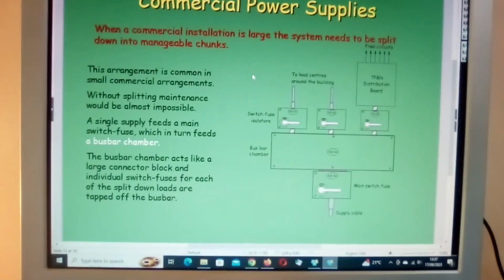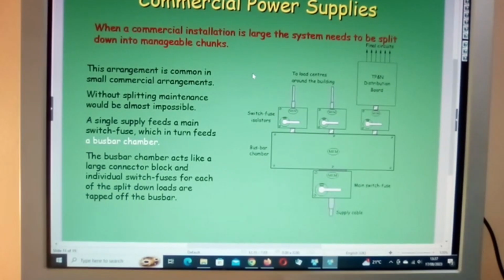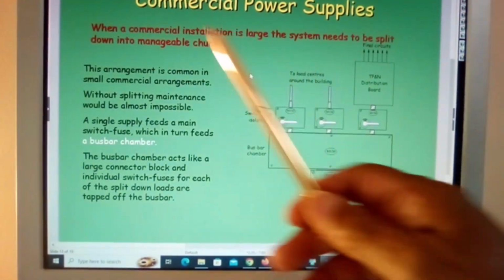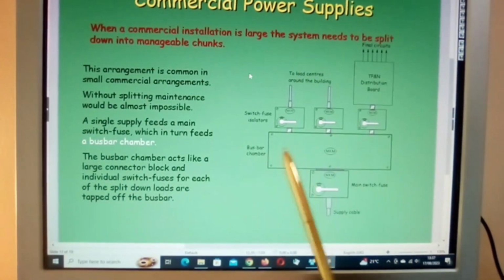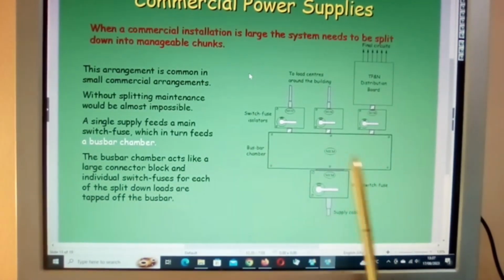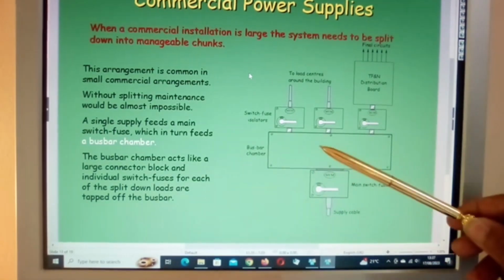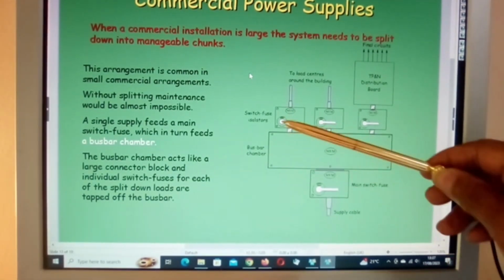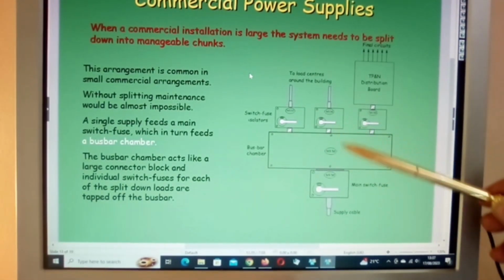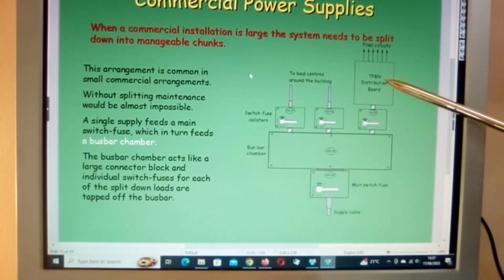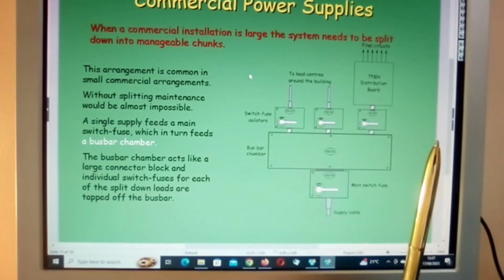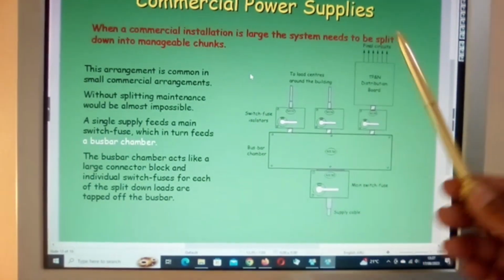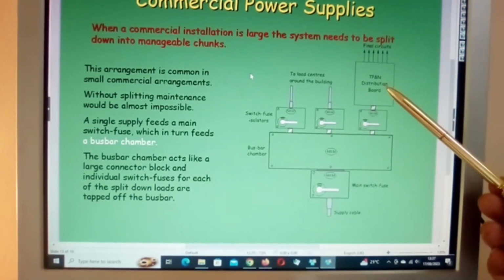And commercial power. Now what this shows you here is how systems are connected. Means of control that you have, this would be a bus bar box. Okay, bus bar chamber. Basically from your bus bar chamber you have switches going to each support. Each switch will control a distribution, three-phase distribution board. Okay, three-phase, let me rephrase that, three-phase and neutral distribution board, of course with earthing terminal.